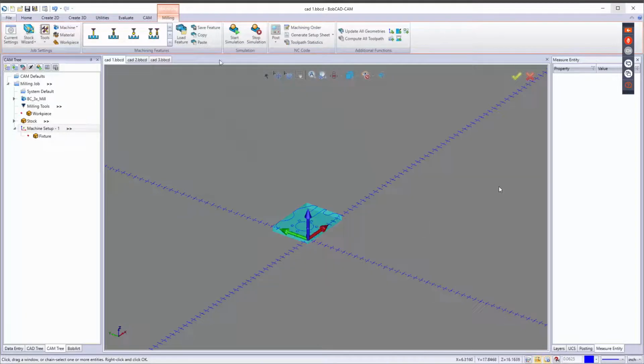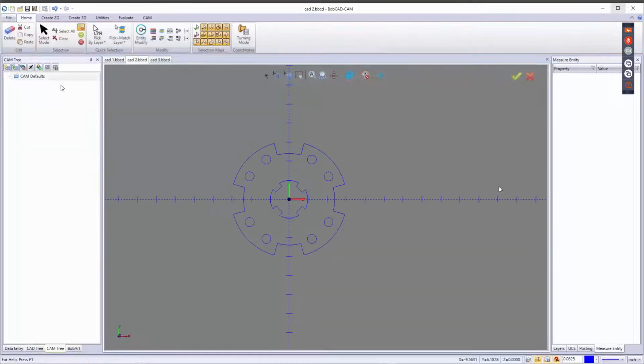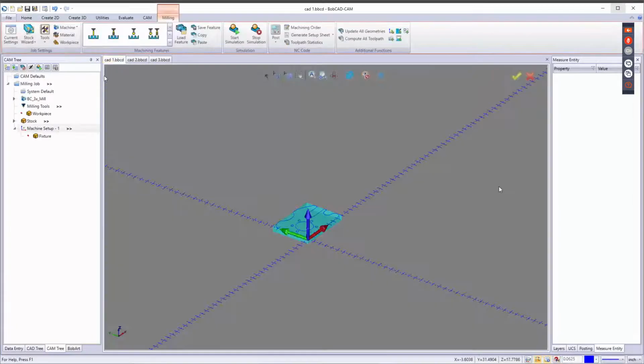Anyways, you can load that feature up, and if everything inside is correct parameter-wise, the only thing you would have to do is reselect your geometry, make sure your depths are correct, make sure your direction is correct, and then compute the toolpath. That's it. Copy and paste does the same thing. I can copy a toolpath or machining strategy from here, bring it onto this one, and paste it in there, or do the same down in the machining strategy.